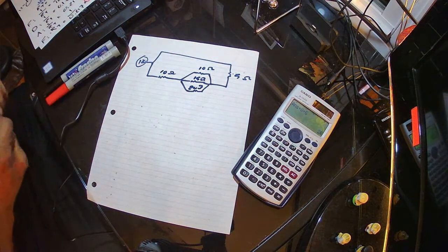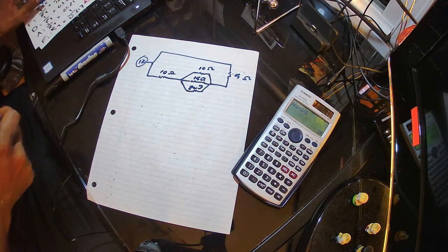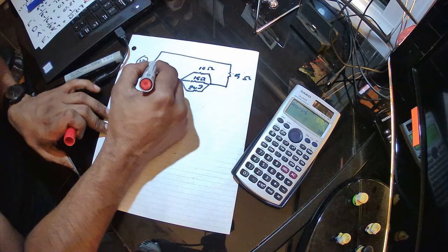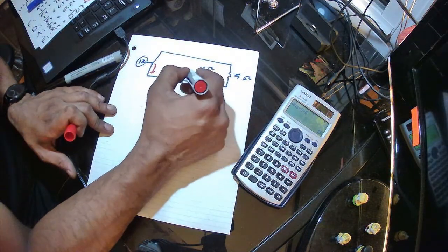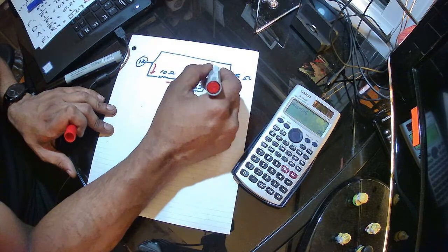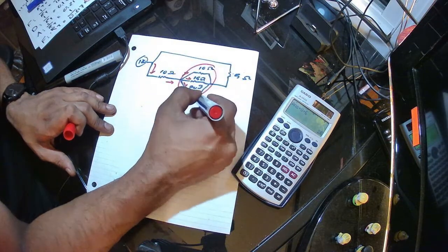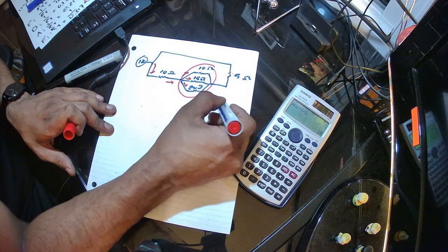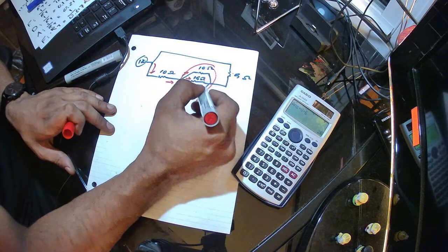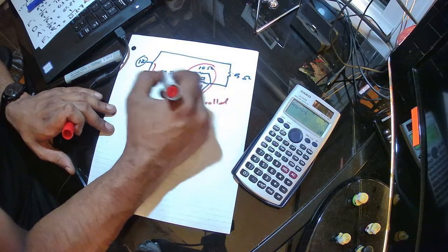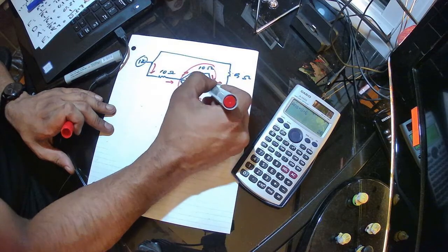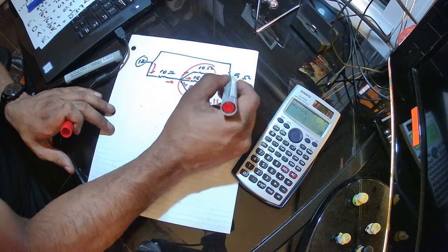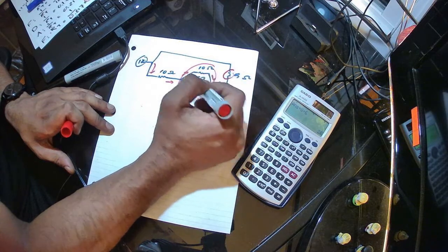The first thing when I look at the circuit is to see what the configuration is. From here I'll follow the current. It's the same. Then it divides in here, so we know these are in parallel, and this total resistance here is in series with this because it's getting the same current, and these currents will merge again to become the same current and go to the final resistance.